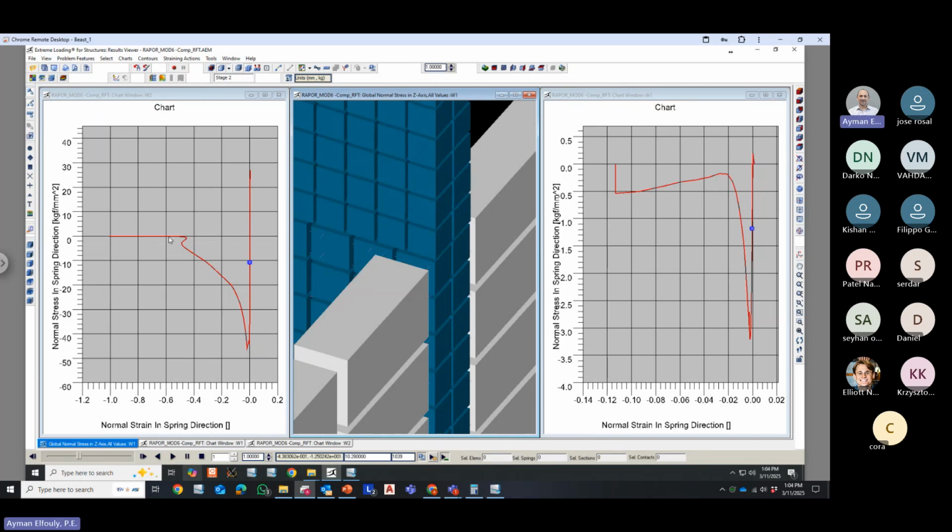This is the reinforcement rebar, and this is the concrete spring. So we see here it's about to reach failure. It reaches failure, and it is now failing. We see here that the spring went into yield in compression and then failed, and hence we see the compression failure happening in front of us.